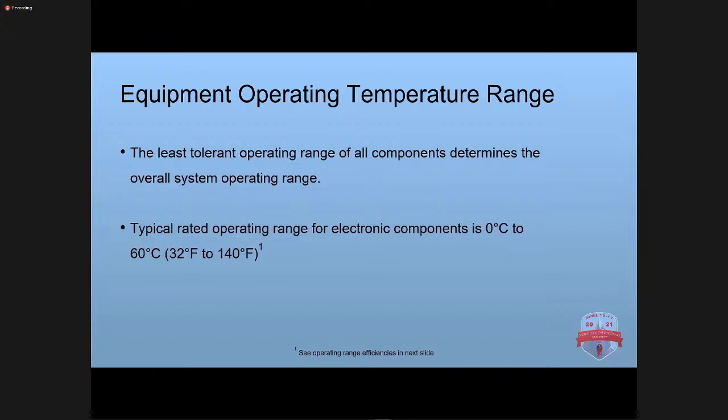And when you're trying to put multiple different parts into an enclosure, say a controller, maybe a BeagleBone or Raspberry Pi and a power supply, you have to look at all of those as an aggregate of the made up system. So when you're looking at operating temperature ranges, you have to look at all the pieces. You can't just find the ones that run to the highest to the lowest range. You have to look at them all. So the context here is, if you're looking at something like that, you may be limited with the operating temperature range on your devices.